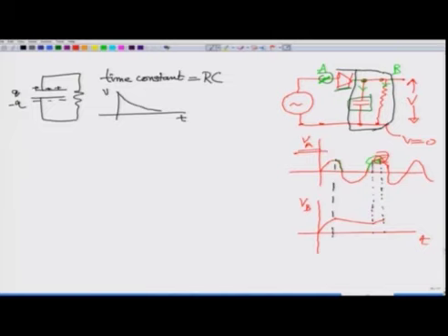So, here the P side voltage decreases, the diode becomes reverse biased, once again discharging starts and this whole cycle will continue. So, it will discharge again like this, once again it will become equal somewhere here and after that again it will be charging and then discharging and so on.